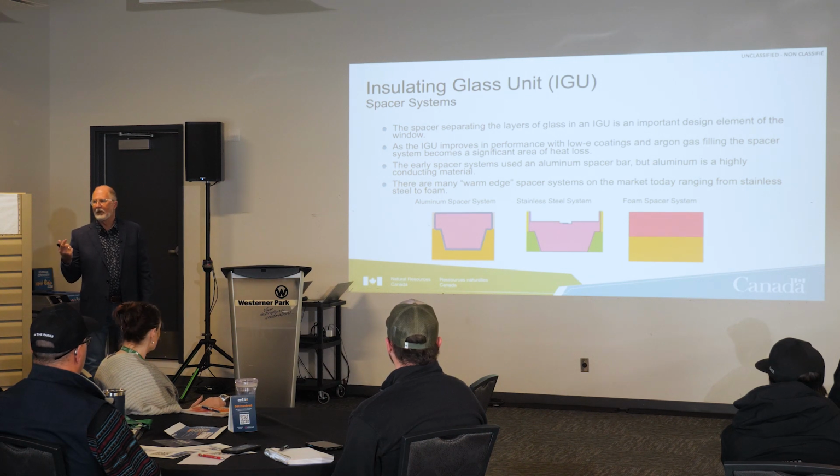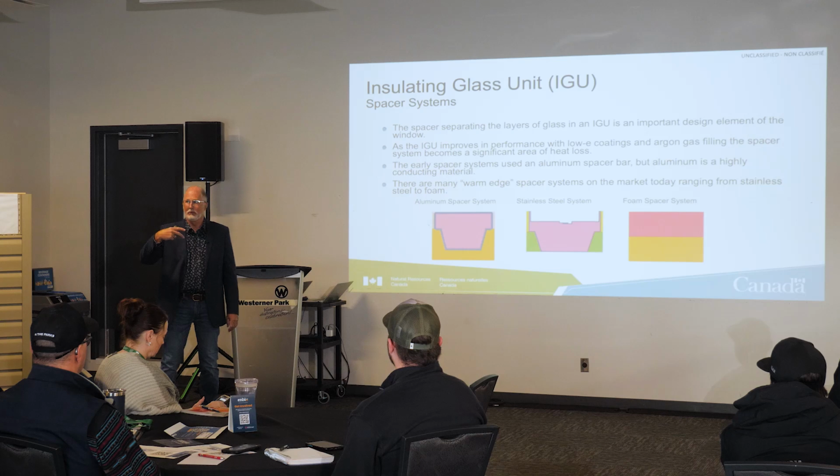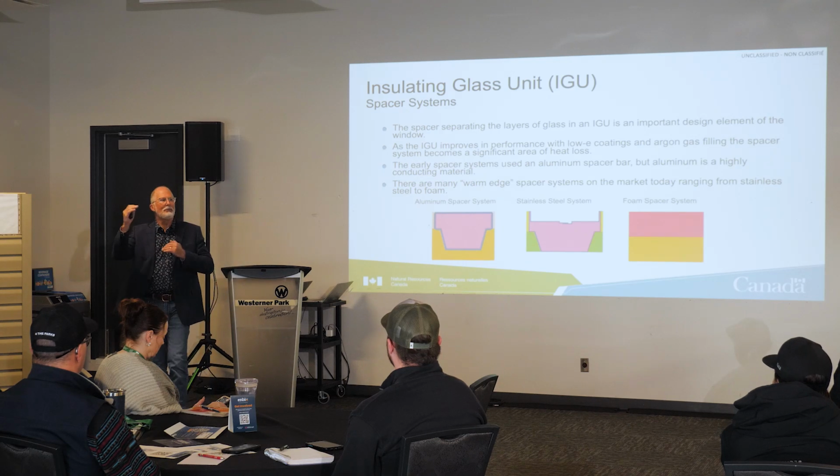So you can imagine on a sunny day in minus 30 weather, it's minus 30 overnight, the sun comes up, it's beating on the backside of the south of the window. That window frame is going to go from minus 30 to plus 30, 60-degree swing in about 4 hours. And then the sun sets and it goes the opposite. So you get these extremes in temperature.